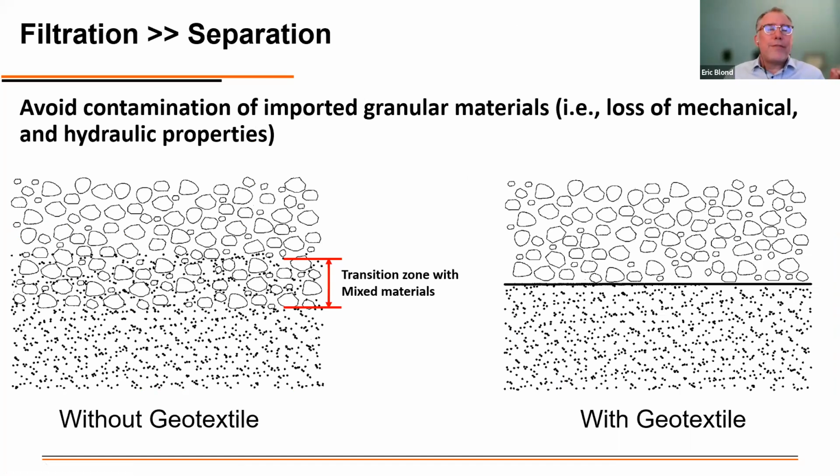Important remark for filtration is separation. What we want to do when we do a separation layer in a structure, we want to avoid mixing of the imported gravel with whatever subgrade is underneath. If the subgrade is mixed with the gravel, we have a percentage of clay or fine grain material within the gravel on a given thickness of gravel, and this gravel will behave like